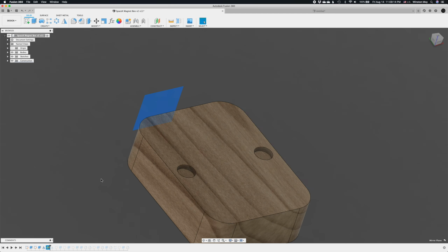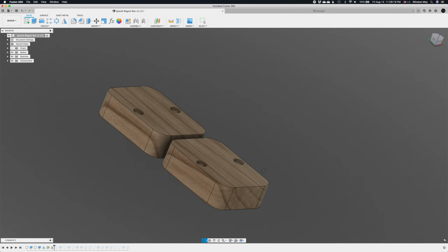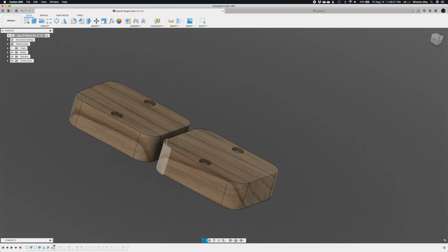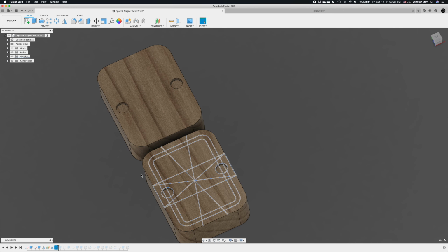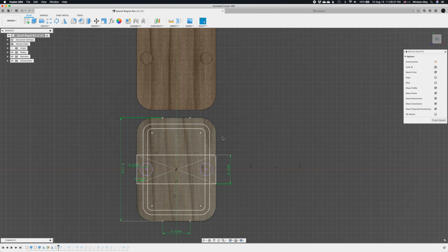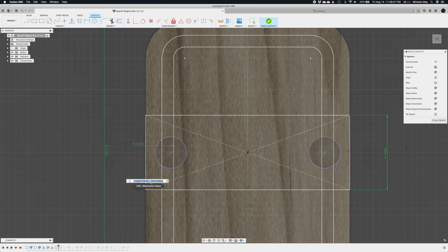I created a mirror plane here. This is how we're going to make the lid. I just start them off basically identically, and then I add a positive feature here, and I subtract that reciprocal feature over here. The next sketch is for that little lip that protrudes out. So here, I guess this first contour is the ledge thickness minus nominal gap.